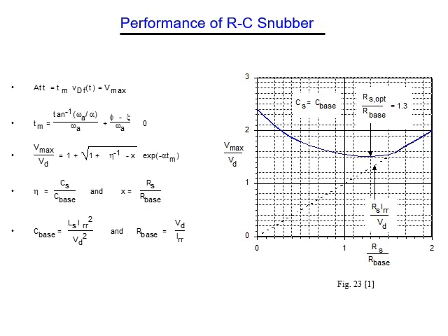If we go through the same procedure to find the maximum capacitor voltage, we see it is not only a function of the capacitor; it is also a function of the resistance. The resistance makes an important contribution to reducing the voltage across the diode.